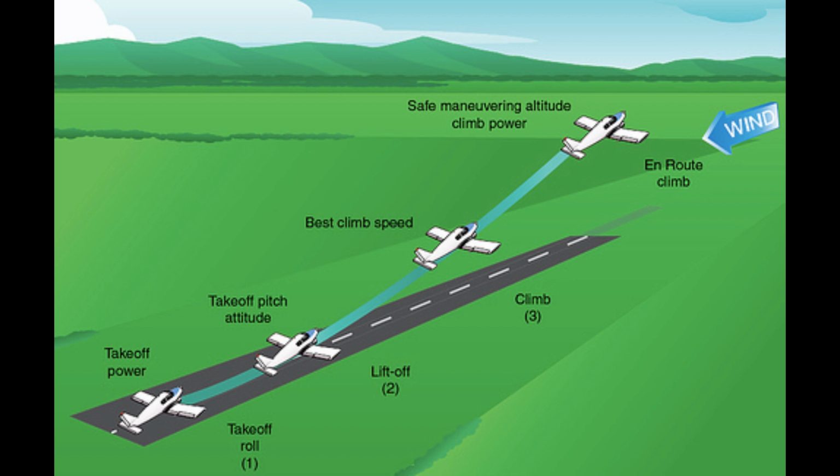Climb at an optimum rate consistent with the operating characteristics of the aircraft to 1,000 feet below the assigned altitude, and then attempt to climb at a rate of between 500 and 1,500 fpm until the assigned altitude is reached. If at any time the pilot is unable to climb at a rate of at least 500 fpm, advise ATC.